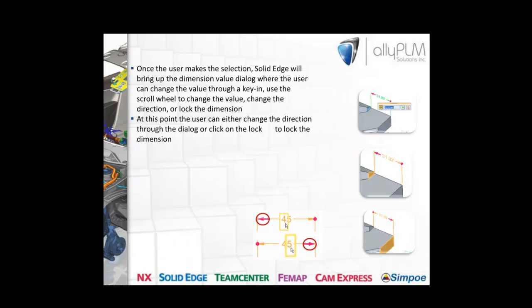For directional 3D edits, it all depends on which side of the dimension value you click. If you click on the left-hand side, you'll notice that the red arrow appears on the left-hand side, and all the geometry highlighted as light blue is going to change. Similarly, if you select slightly right of the dimension value, you can change the highlighted faces.